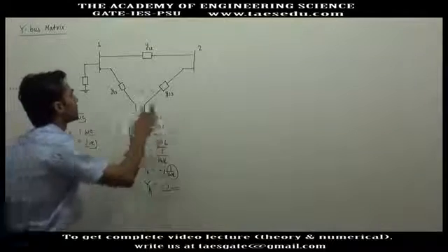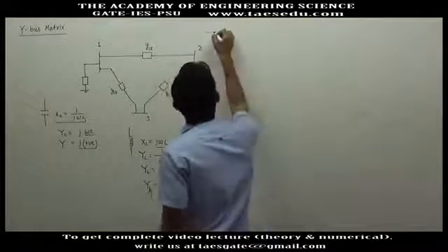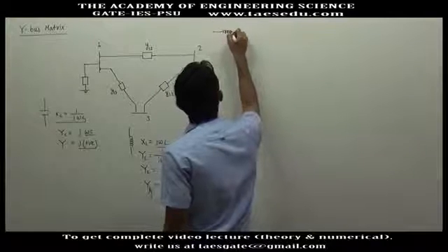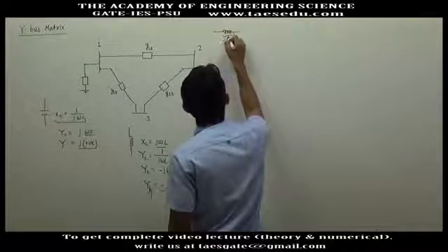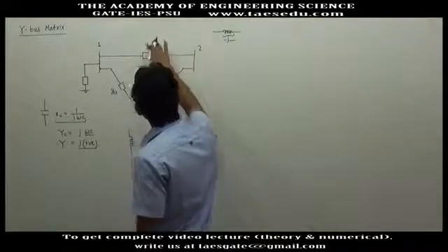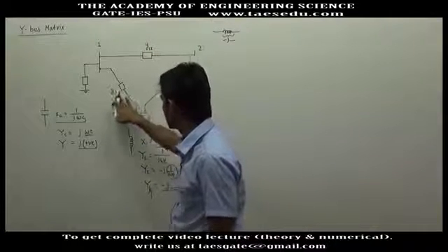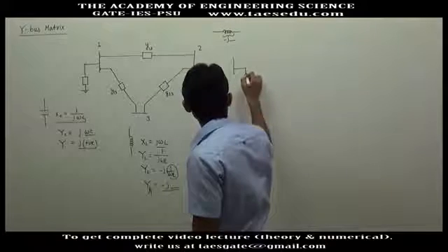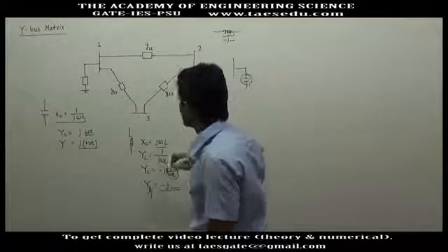When two buses are connected through a transmission line, the reactance dominates, and the admittance of the reactance will be minus j times some magnitude. So normally you will have a negative admittance here, here also, and here. Normally buses are connected with a shunt capacitor, so the admittance of the capacitor is positive.